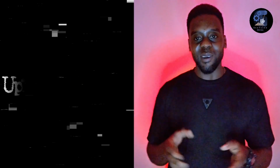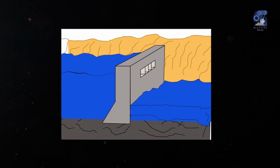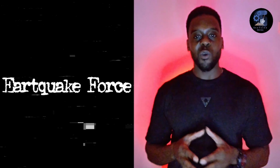Because of the permeability of the foundation materials, water seeping through the pores and the fissures will exert an upward force on the base of the dam. If this uplift force is not properly monitored and controlled, it will develop and compromise the overall stability of the structure. In earthquake-prone areas, the gravity dam will be heavily subjected to ground movements.